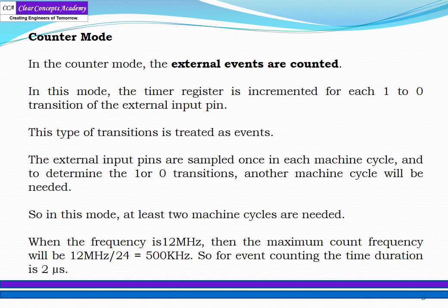In that case, the external interrupt pin is disabled, because even if there is an external interrupt, it will not count that, it will not take care of that external interrupt, and it will only count the internal pulses of the microcontroller, the internal machine clock.